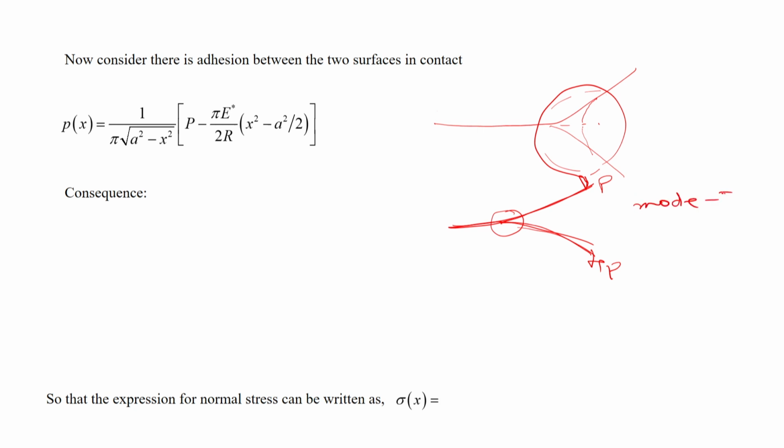Then there is another way to open the crack: one material is something like this, another material is something like that, and they apply the load something like that. This is in shear, so this is called a mode 2 crack. Over here we do not need to worry about mode 2, because we do not consider that. Let us say it is about mode 1 only, and in mode 1 what are the stresses that develop in the crack.